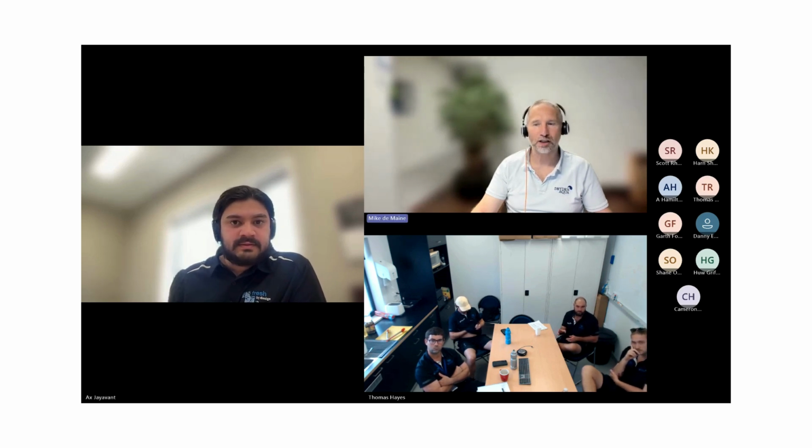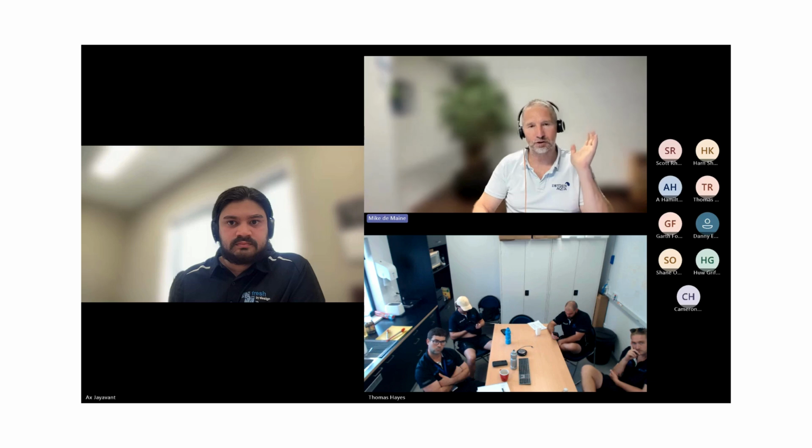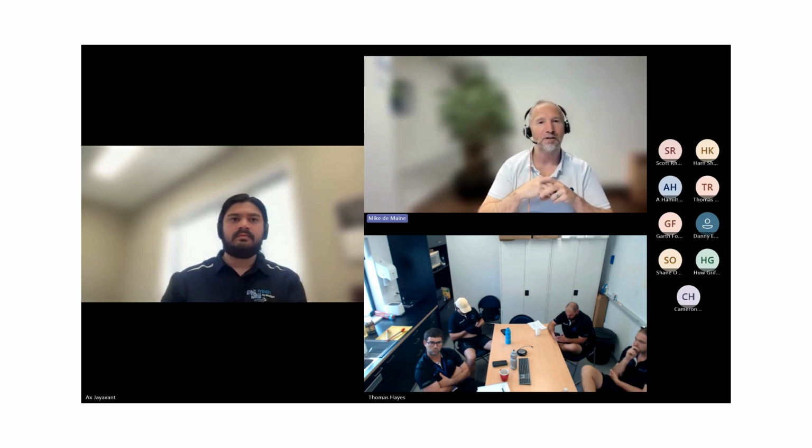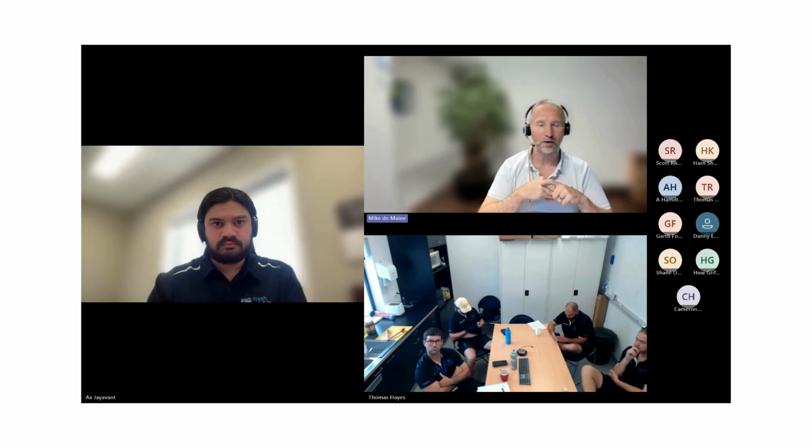Yes, you can actually. In applications like I have in South Africa, we've got a lot of groundwater applications where they have both high organic load because of sewage contamination and also heavy metals. Africa's got a lot of heavy metals in the ground. So then we can mix the two. You'll have the AFM standard and the AFM NG in the same filter vessel together, focusing on both parts. So yes, that is very, very possible. And we do that quite a bit in Africa.